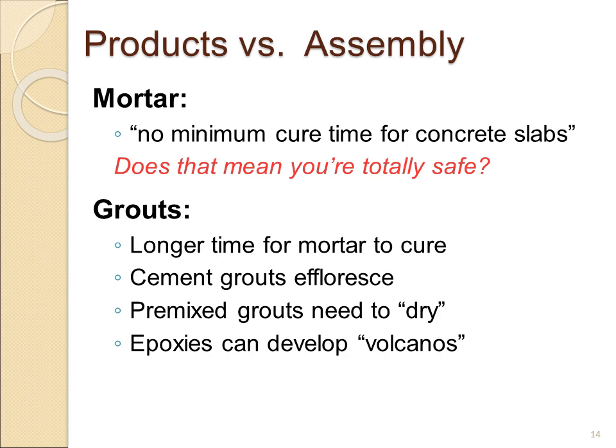For example, with mortar, there are advertisements for mortar that say there's no minimum cure time for going over a concrete slab. And when we look back at the picture that we showed earlier of the efflorescence underneath the tile, what did that show? It showed, well, yes, the mortar wasn't broken down, but moisture did affect that installation. Same thing with grouts. It'll take a longer time for the mortar to cure. How is that going to affect the grouts that you're using?